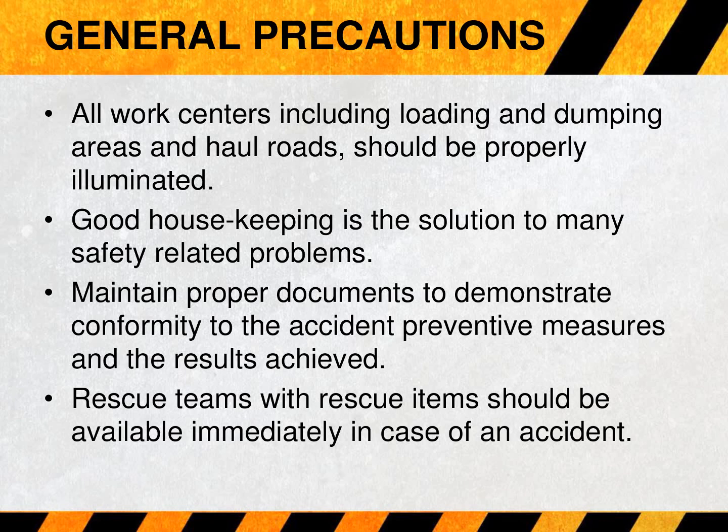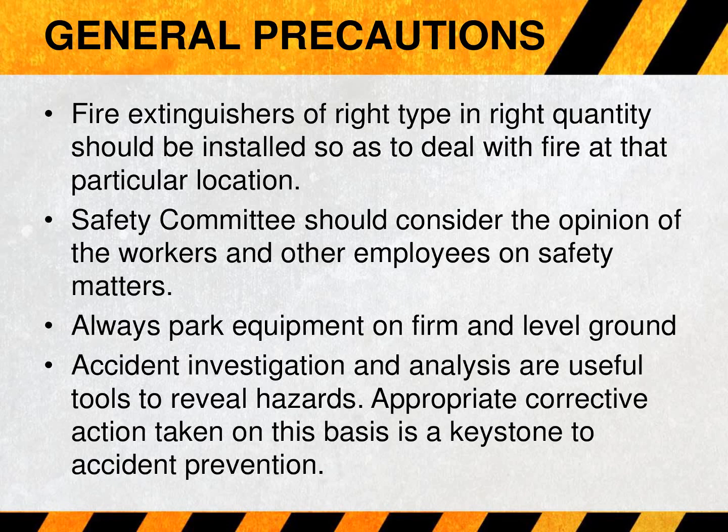Rescue teams with rescue items should be available immediately in case of an accident. Fire extinguishers of the right type in the right quantity should be installed so as to deal with fire at that particular location. The safety committee should consider the opinion of the workers and other employees on safety matters. Always park equipment on firm and level ground.